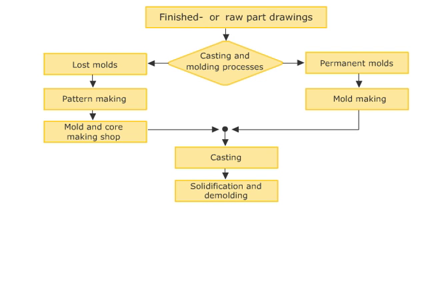During subsequent cleaning of the casting, molding material, as well as sprue and riser, are removed from the casting. Casting seams are flattened as well. If needed, the surface can then be processed with water or steel shot blasting to improve the surface finish. If possible, any subsequent heat treatment should be avoided, as it causes additional costs.